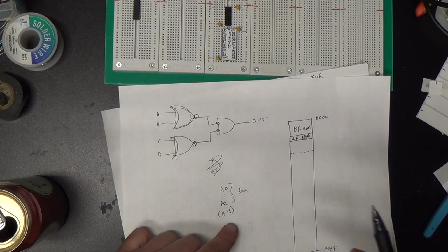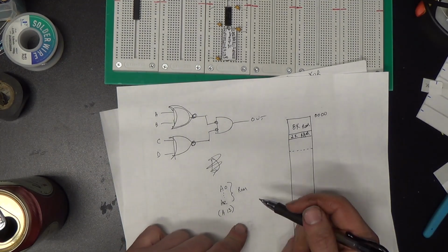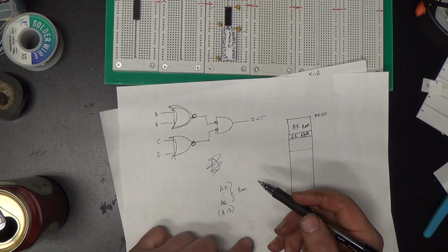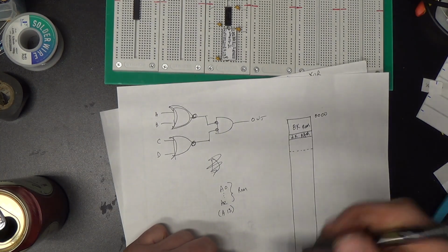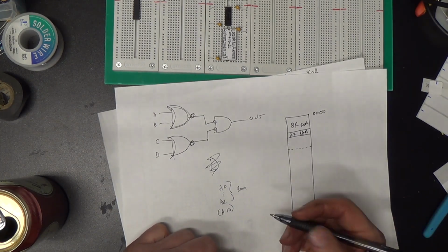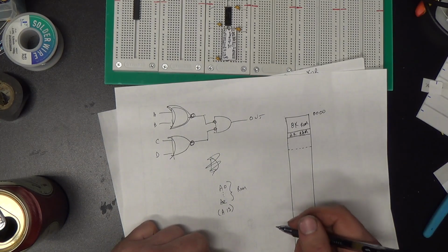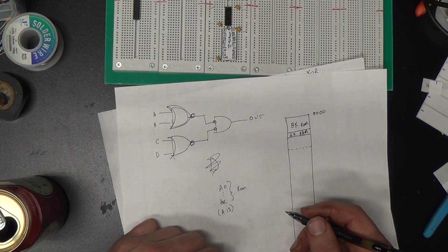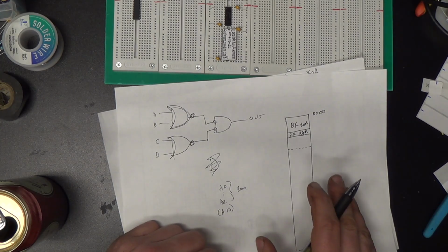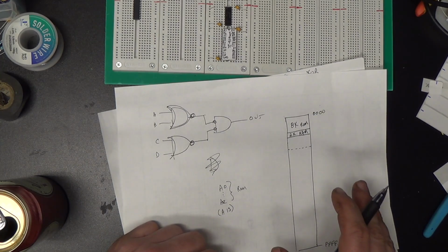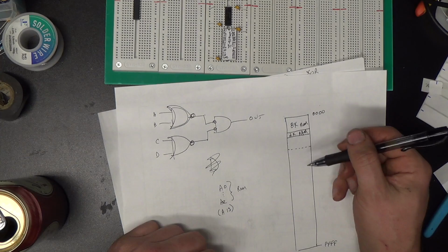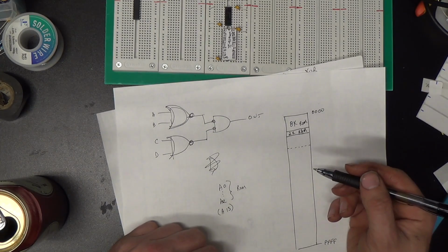Now, this is partial address decoding. You won't see partial address decoding in very many modern systems because with the advent of things like programmable logic, it's very easy to design circuits that don't benefit from partial address decoding. But back in the day, this was very common. For an embedded system that would never be expanded, it didn't matter if some of it was mirrored in the memory map.